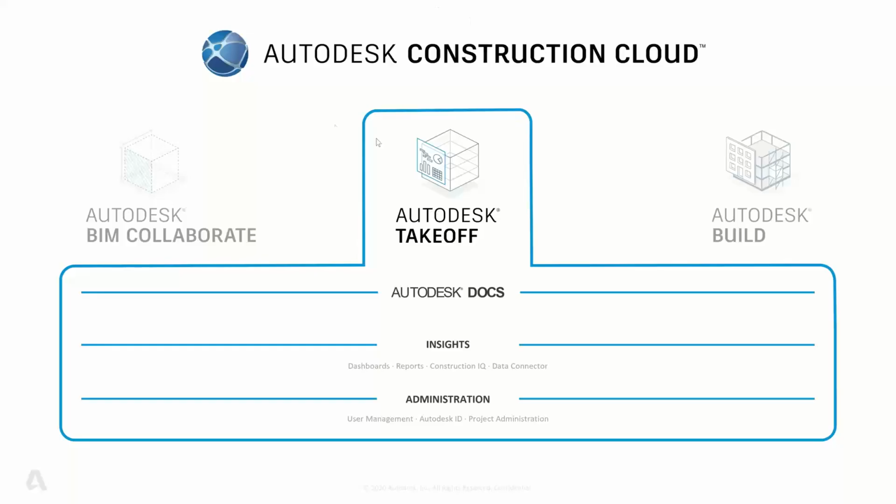So basically what we were going to show is some of the different features of BIM Collaborate, and specifically, probably beyond what he was just showing, some of the coordination under the model coordination feature of BIM Collaborate. And one good feature, just kind of explaining it without showing it, is that when you publish different model views from the Revit end, you can have a collaboration model configured and publish 3D views, certain isolated views. So let's say we have a collaborative model that has all of the disciplines, architecture, MEP, and structure, all in one aggregated space of a Revit project. You can isolate different views and publish them from Revit to create coordination, clash detection in the cloud.